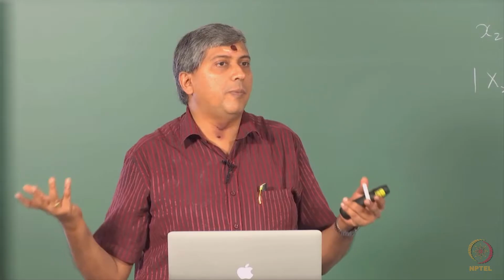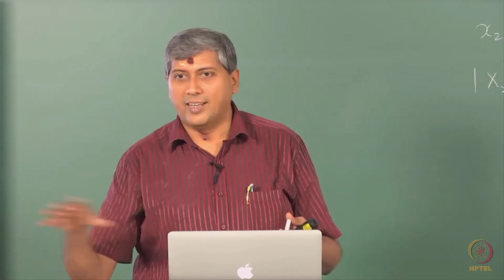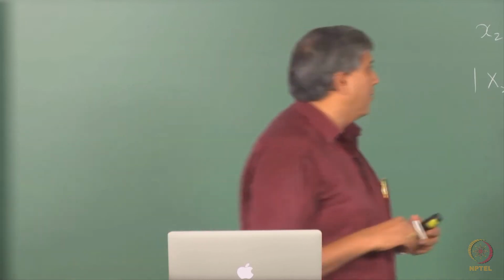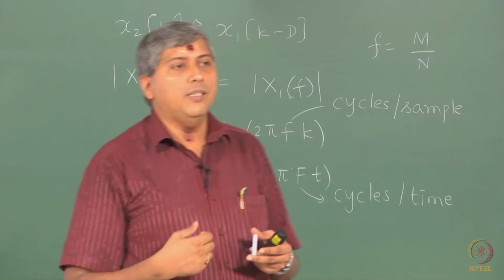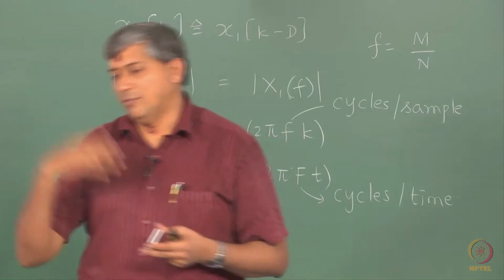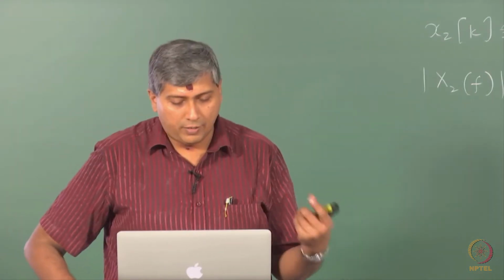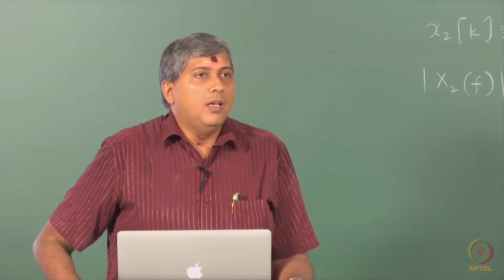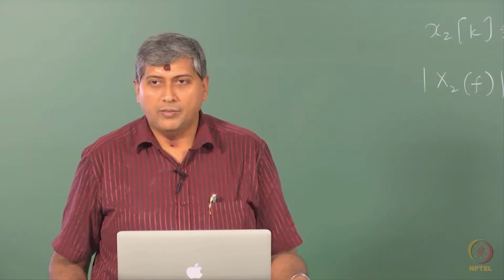Why is that? Because the period of a continuous time signal belongs to the real number set, whereas the period of a discrete time sine wave belongs to the natural number set, that means positive integers. Therefore, not all discrete time sinusoids are necessarily periodic, you should keep telling yourself that until you know by heart.